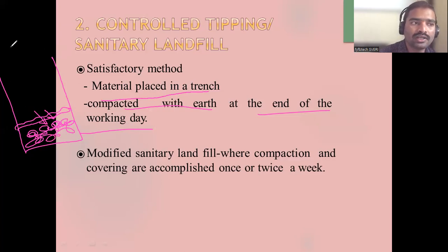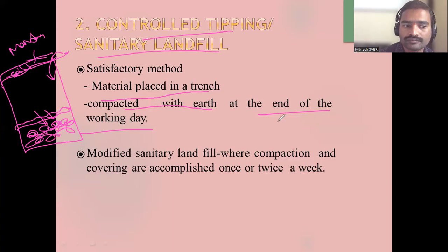So today is Monday. Today morning they have started filling the waste. After the end of the day's work, they will put the soil, they will compact it, and they will finish. They will not open it again. That is sanitary, compact, controlled tipping or sanitary landfilling.